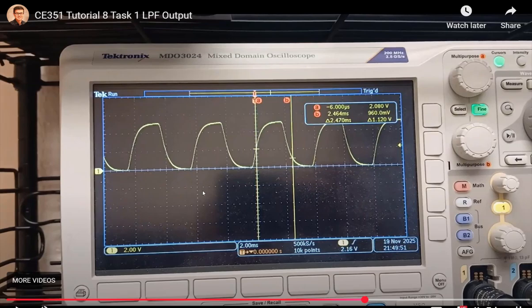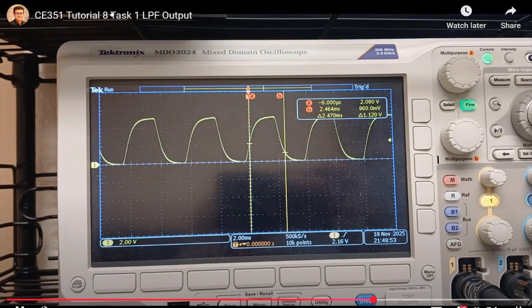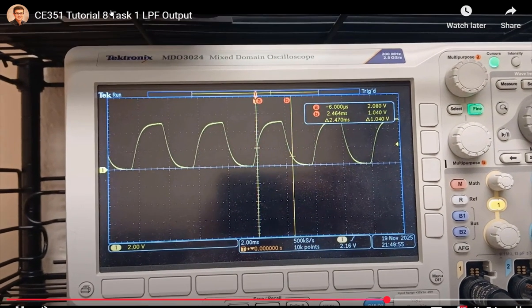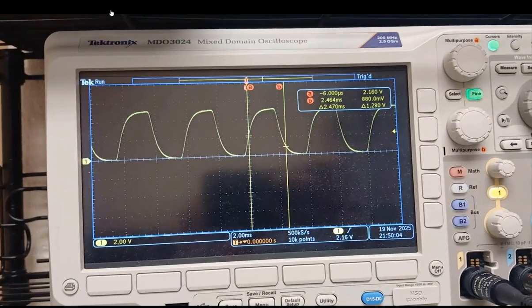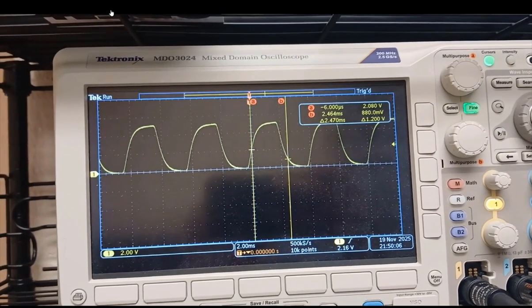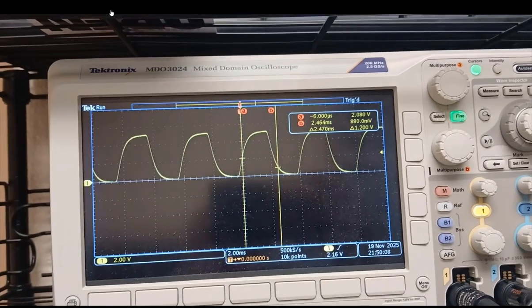So we'll change the duty cycle of the PWM. I should have that display on the channel too, but I didn't do that. But you can imagine there will be a duty cycle change. It's just basically a 50% digital signal, and it's getting delayed because of the low-pass filter. Then you press any key on the keyboard, just any key, to cycle through all the duty cycle values in the array, and it's going to show you different time delay effects.